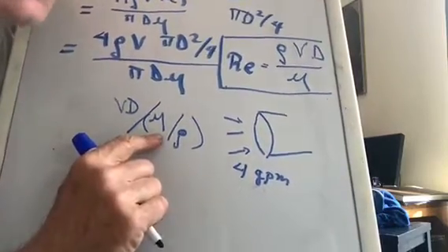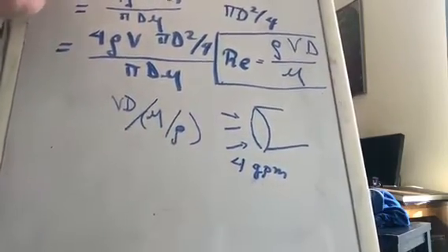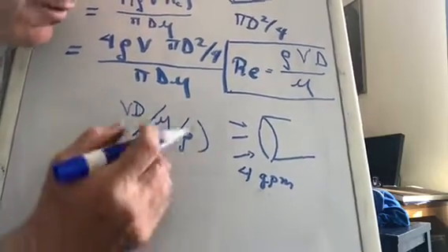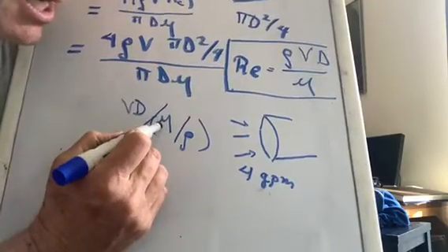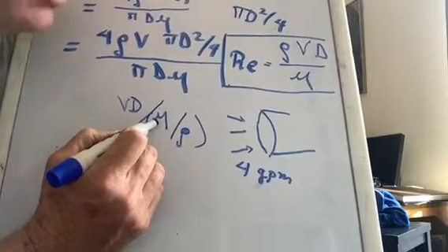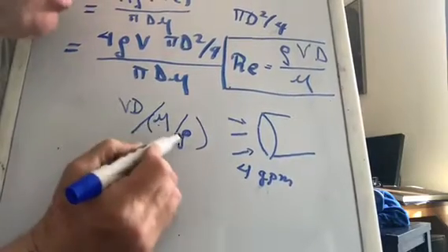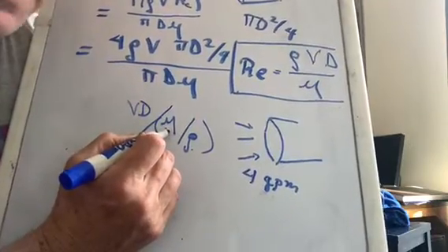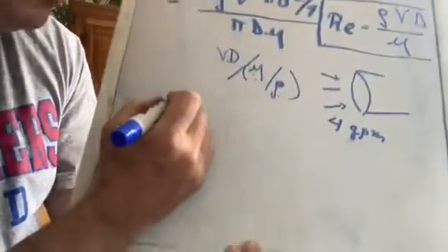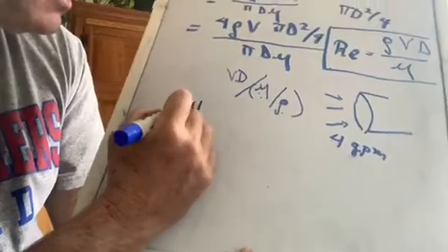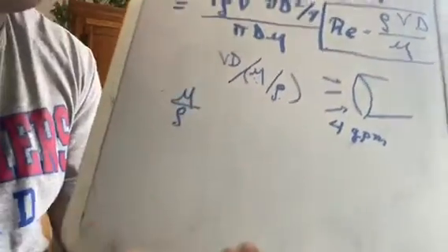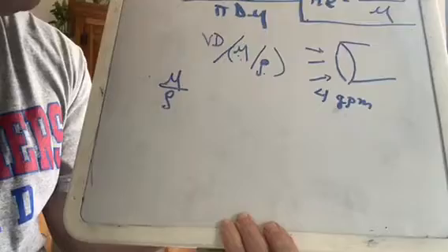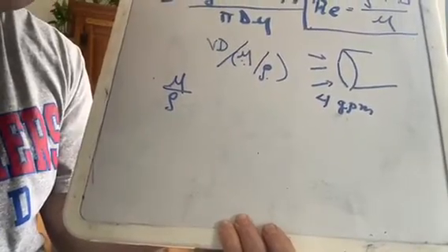Okay, how about the viscosity? We'd want the viscosity to be very large. So it turns out that what we'd want is to prevent turbulence, we would like a large mu and a small rho. So it turns out that this factor here, mu over rho, is actually, in a sense, tells us for a fluid how unlikely it is that the fluid is going to be turbulent.